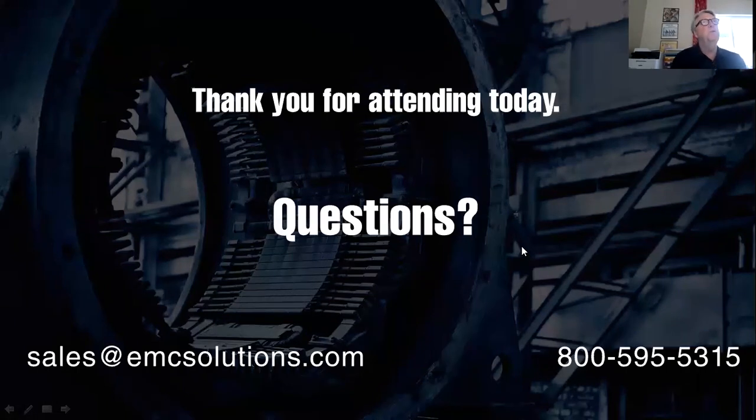And so most people go with the 3% just because they don't want to spend a little bit more on a 5%. But if you specify a 5%, it'll do a better job both on harmonics and on surge protection. And it doesn't cost that much more. The line reactor is a fairly small part of the drive. So maybe the 5% line reactor might be 50% or 40% more than a 3% line reactor. But since it's such a small part of the cost of the drive, it really doesn't make much difference in terms of the drive.